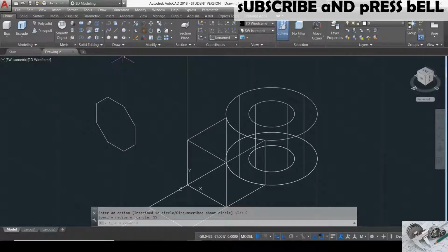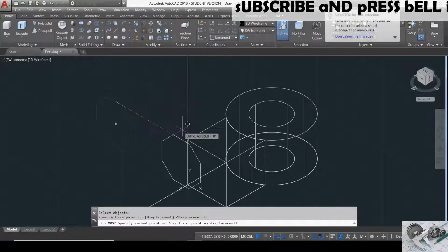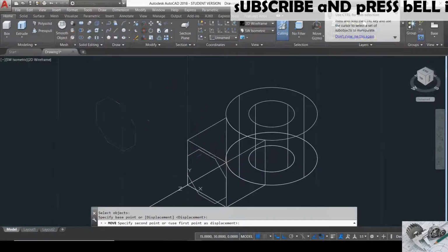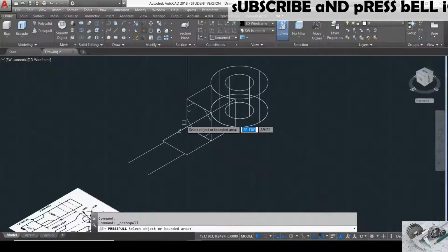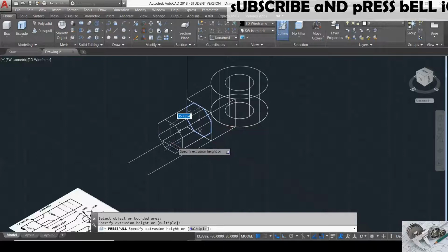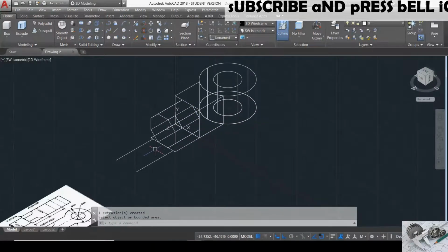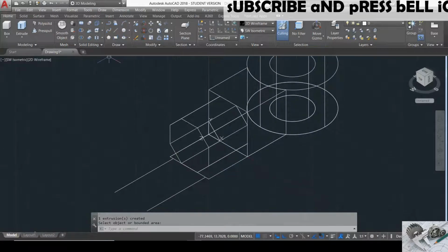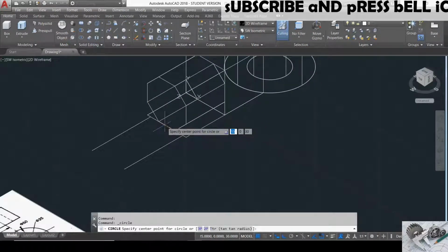So select the octagon shape from the polygon, 8-sided. Select the circumscribed option and the radius of the circle will be 15 mm, as it is given that it is 30 mm size. Select and move the octagon onto the face of the body, then press pull it. It is 30 mm in length.